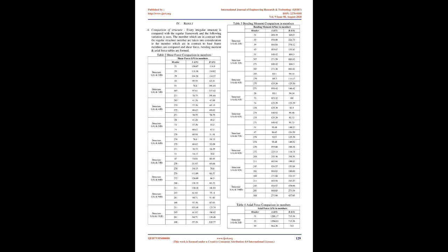The structure is intended for residential purposes. The ground story is planned as a parking floor, thus making the structure an OGS type of building. The symmetrical configuration pattern is taken and complete analysis is carried out using live load, dead load, and seismic loads in the STAAD Pro V8i software.